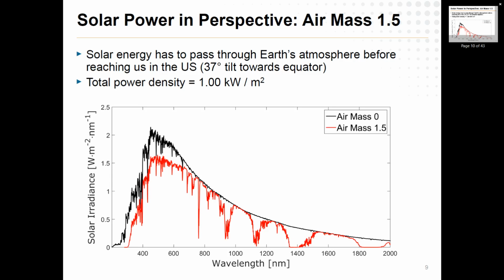It's a common phrase you'll see as the universal standard for the average light insolation you can expect being here in the US. And they even make special test stations with specially calibrated lamps that give you one AM 1.5 spectrum by which to measure and calibrate your solar cells. You can think of it as a measure of performance.